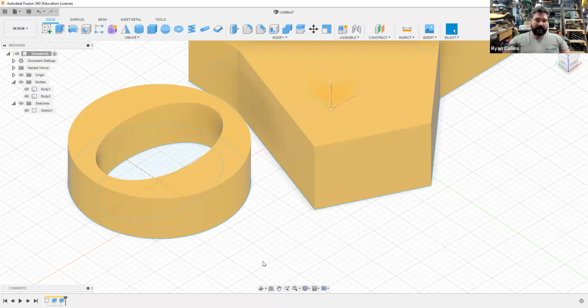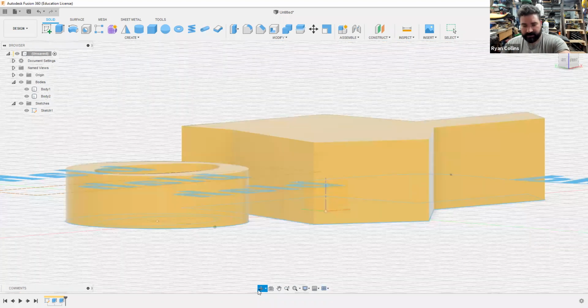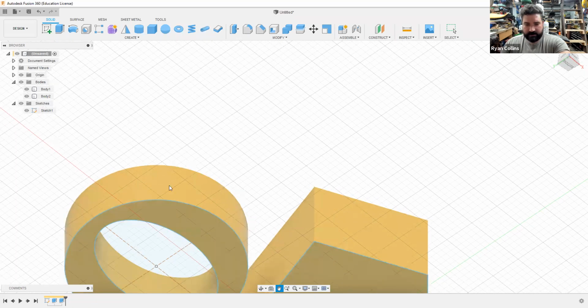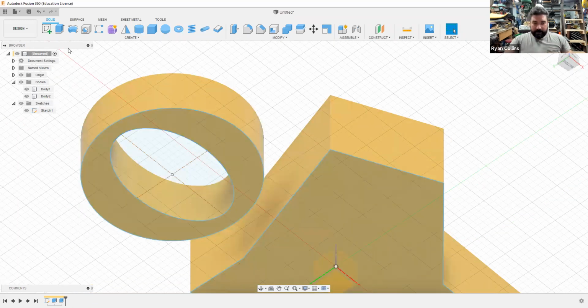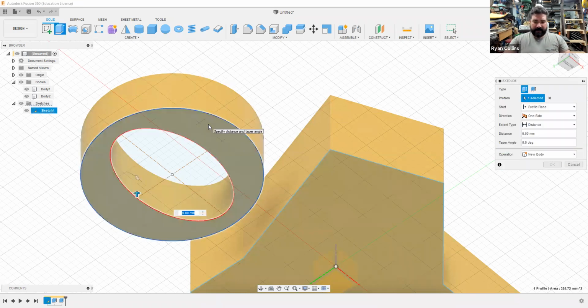Well, now let's say I wanted to create something below it, or rather, I also wanted there to be a bottom to this. I didn't want this to just be a hollow circle or kind of cylinder. I wanted this more to have a bottom to it. So what I'm gonna do is press and hold Shift and orbit up, or again, you can just use the orbit tool. Slide it, pan over so I can see what I'm doing. Select extrude again. And now I'm going to select that outer one, but I'm also going to select the inner one. Well, now I'm going to drag downward.